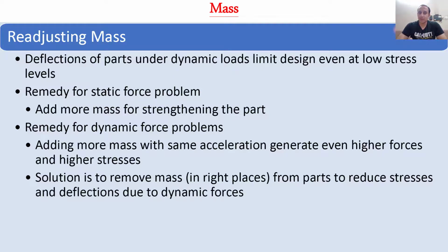Okay, so in dynamic analysis, in order to further tweak the design, we need to remove mass at definite points from definite locations. In this way we can further reduce the dynamic forces, and further improve the dynamic performance of the machine, system or mechanism. We will see how and from where we can remove the masses when we discuss the topic of balancing.